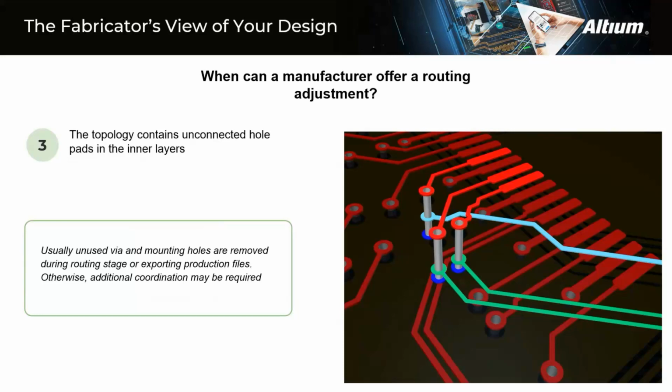The second one usually deletes remaining unconnected pads by default when exporting the files. Manufacturers generally prefer not to use extra pads because they increase the wear of the drill. If for some reason you purposely keep unused pads and put them in the Gerber files, you may want to mention this when ordering the bare boards from your fabricator. After all, the manufacturer can, as a part of the typical preparation process, remove the pads that are not even mentioned.